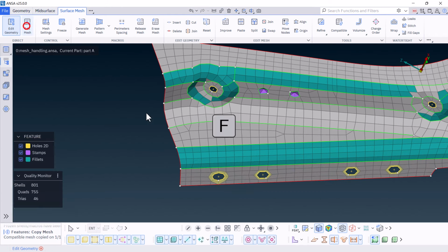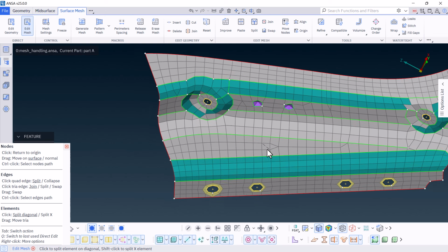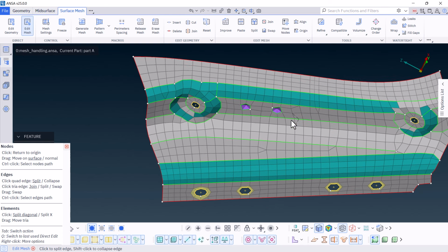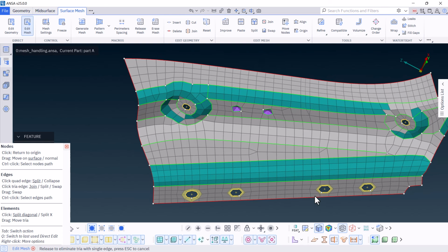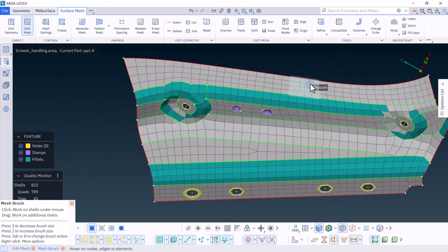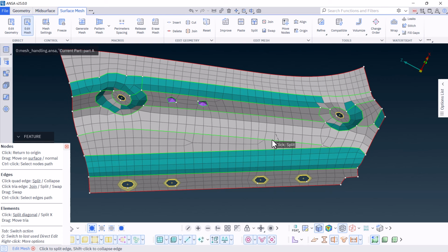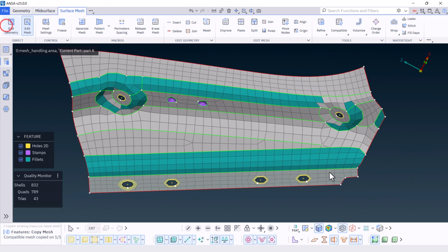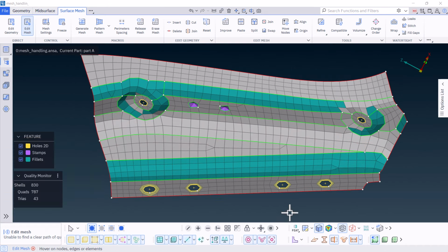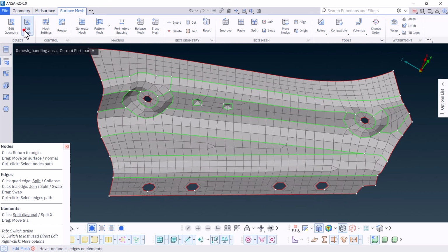Unfreeze the macro area to be able to make any last modifications. Examine the model carefully for any false elements that may disrupt the flow of the mesh. Use the direct edit tools to improve the respective areas. Let's make quickly some final modifications to reduce the number of triangle elements. Change the draw mode and lastly zoom out to inspect the mesh and proceed with making any other changes.